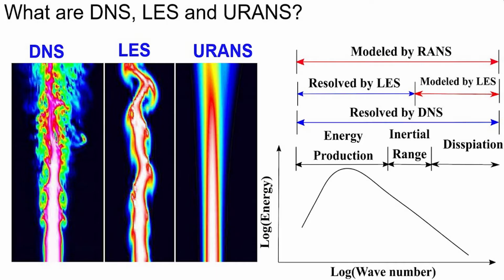A deep understanding of CFD is not necessary to understand this project, but I will just briefly cover some of the concepts to explain some of the decisions I made whilst building the model. There are three main types of CFD: Reynolds average Navier-Stokes, large eddy simulation, and direct numerical simulation. RANS, LES, and DNS, respectively. RANS models are the least accurate, only solving on a large scale and modeling everything else, whilst DNS solves everything. LES solves more than RANS, but still models the smaller scales.